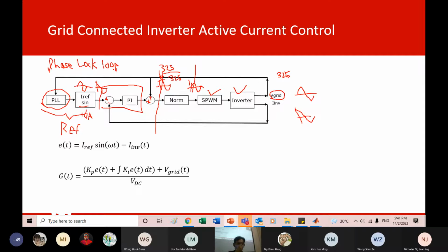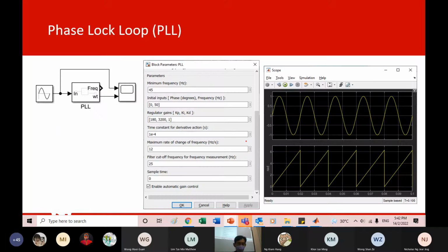Okay, any questions? It's important. When you design an inverter, you need to know two things only. One, topology. When I talk about DC to AC, single phase, four transistors connected, that is the topology. Second is the control method: voltage feedback, grid connected or not. So you need to know this. Okay, so now let's move on.